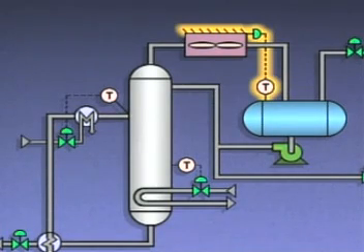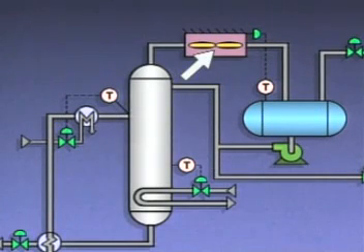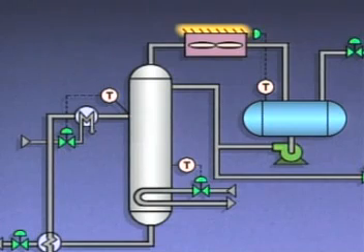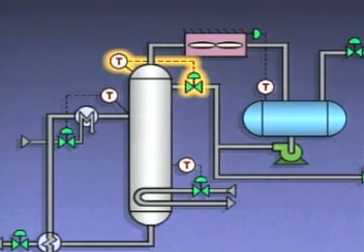Major temperature changes in this control loop are accomplished by starting and stopping the fans in this fin-fan condenser. The control loop makes fine or trim temperature adjustments by adjusting louvers in the path of the forced air from the fans. This system has one secondary energy control loop. It regulates the amount of external reflux that is sent back to the tower to control condensation in the tower.